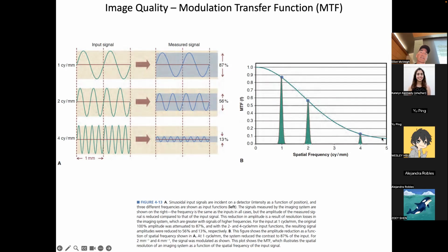And that curve is called the modulation transfer function of that imaging system. Very important concept. And the modulation transfer function tells you how the high frequencies roll off in amplitude when you're trying to image an object. You can't have infinite spatial resolution, like infinite precision on small dots and edges. Eventually, they roll away for any imaging system. This function tells you precisely how your system does that, right?